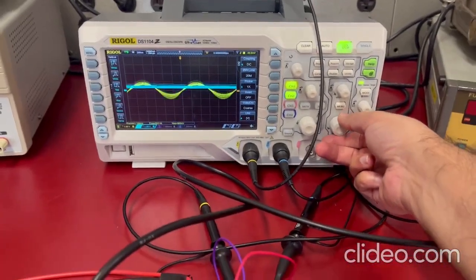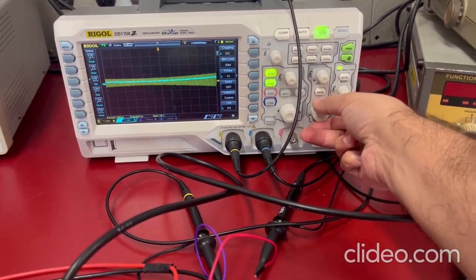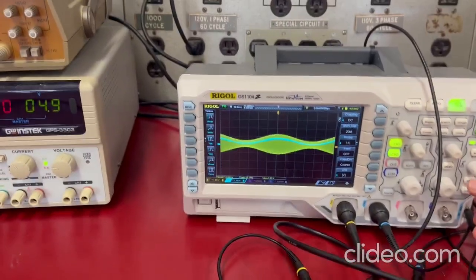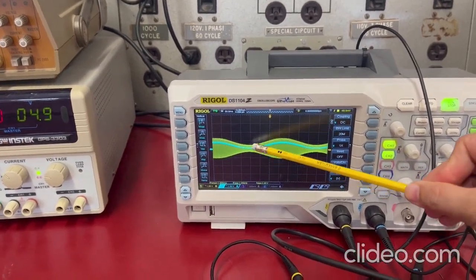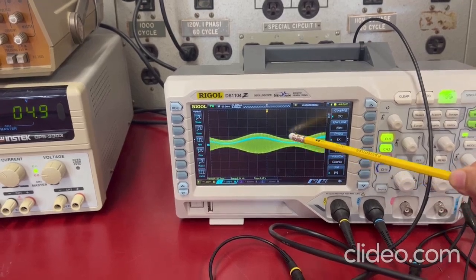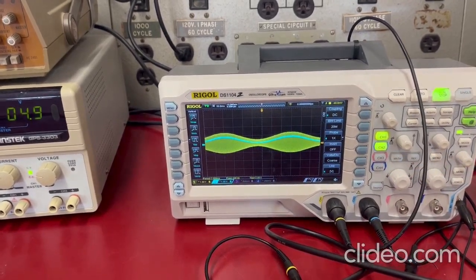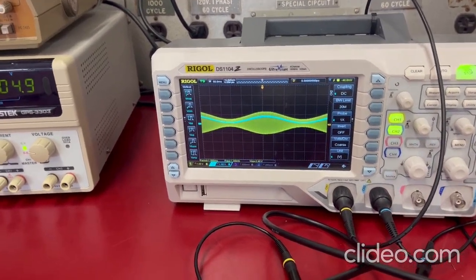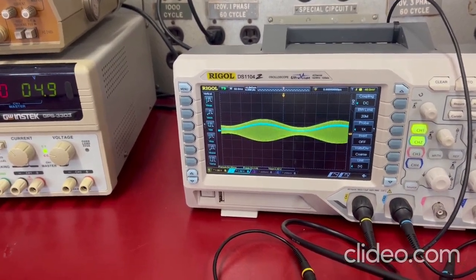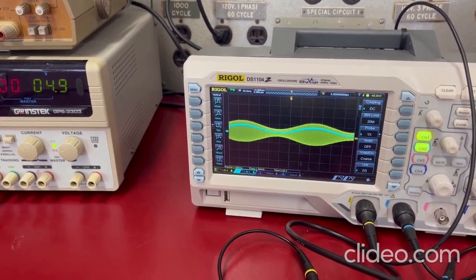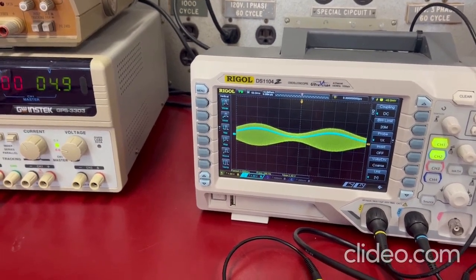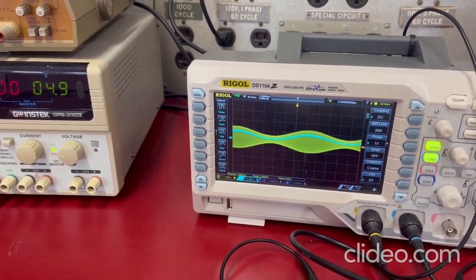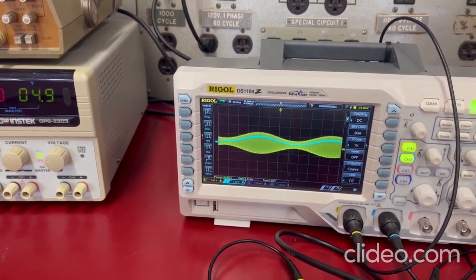To see the effect, you have to reduce the time scale. You can see on my output that my input signal is AM modulated, and you can see in the output also that the rectified output is also AM modulated. And you can see from this that the peak rectifier output rides on the top of the waveform of your AM signal. It's a little bit less because of the voltage drop across the diode. Thank you.